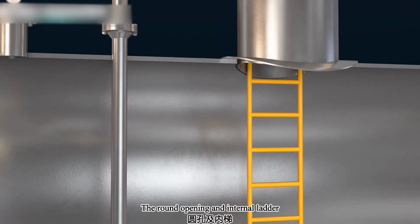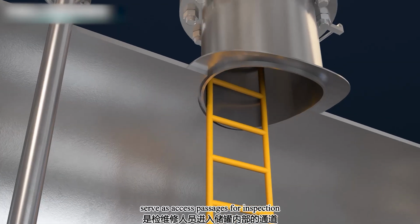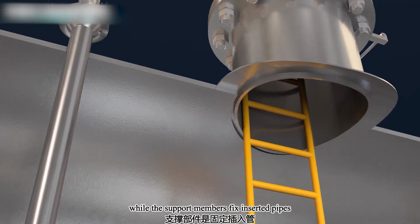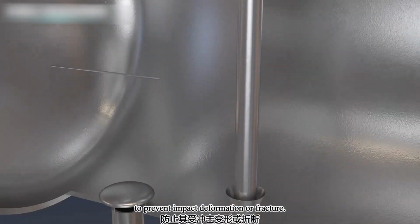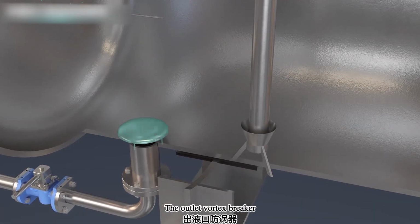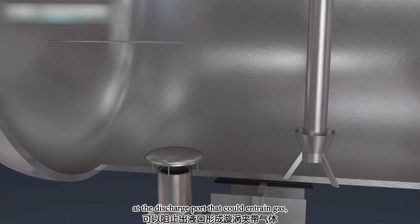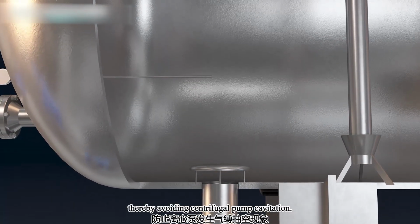The round opening and internal ladder serve as access passages for inspection and maintenance personnel to enter the tank interior, while the support members fix inserted pipes. To prevent impact deformation or fracture, the outlet vortex breaker prevents vortex formation at the discharge port that could entrain gas, thereby avoiding centrifugal pump cavitation.